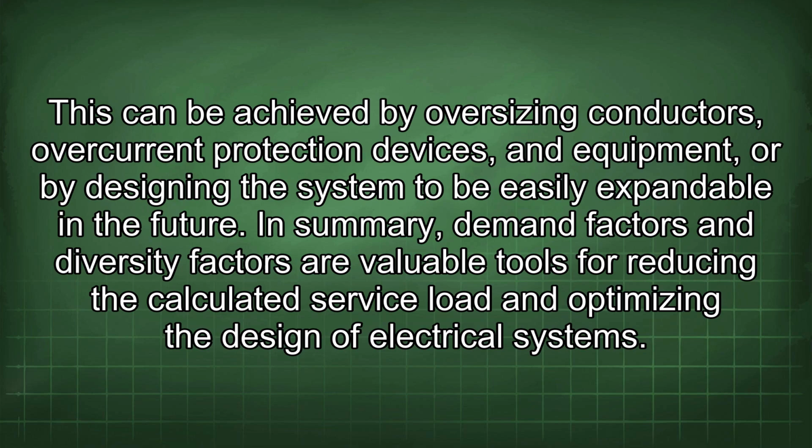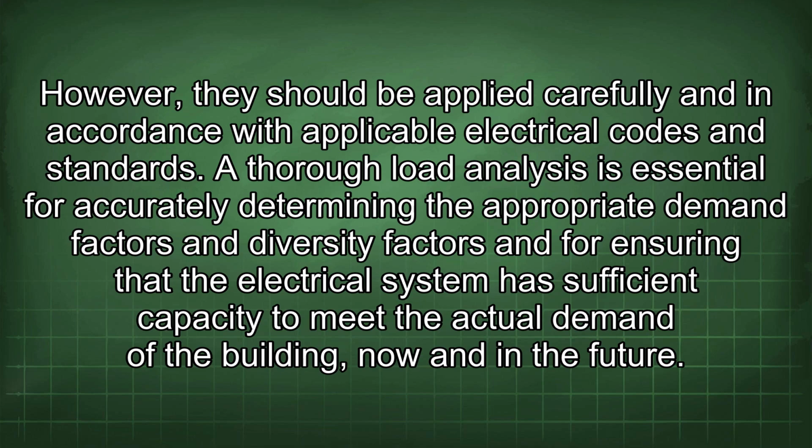In summary, demand factors and diversity factors are valuable tools for reducing the calculated service load and optimizing the design of electrical systems. However, they should be applied carefully and in accordance with applicable electrical codes and standards. A thorough load analysis is essential for accurately determining the appropriate demand factors and diversity factors and for ensuring that the electrical system has sufficient capacity to meet the actual demand of the building, now and in the future.